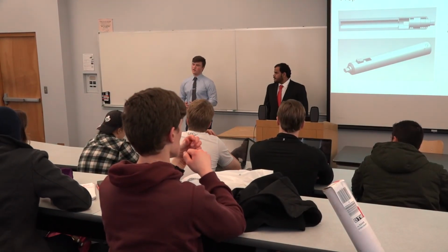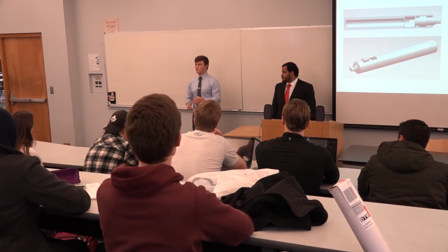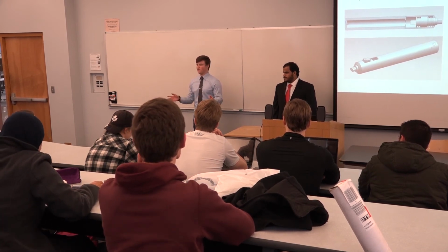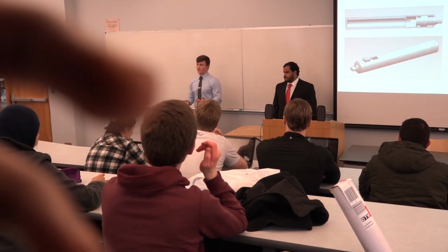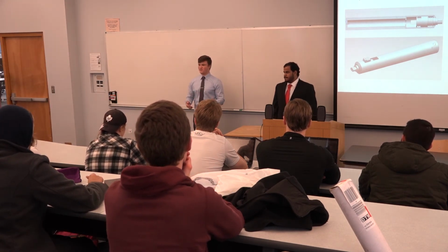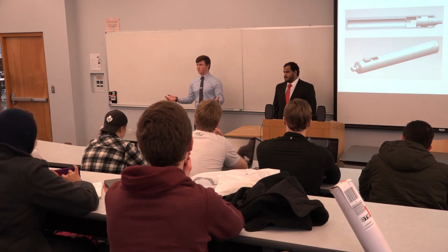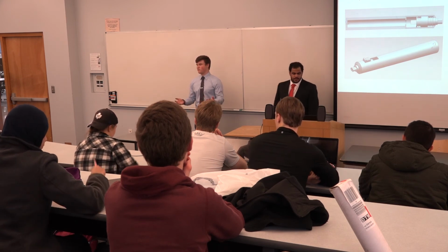The reason we couldn't just have a timer or something like that is that those were in our initial designs, but after the expert interviews, basically everyone we brought that idea up to said it wouldn't work because of the large difference in duration of times for surgeries. But with our device, the same protocols would be in effect. You're still supposed to remove the batteries, and you're still supposed to take off the tip. It's just to provide one extra thing in case someone forgot to do one or all of them. Hopefully these extra measures would help prevent the fire.